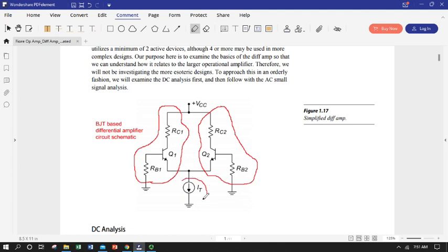What's probably new for those of you who took semiconductors is instead of an emitter bias DC voltage source, we have this theoretical constant current source, and this is called a constant current tail when we talk about op-amps and differential amplifiers. But we can model it with just a big high impedance resistor and a voltage source, so we can analyze it the same way.